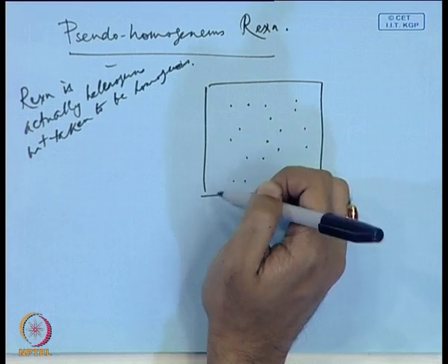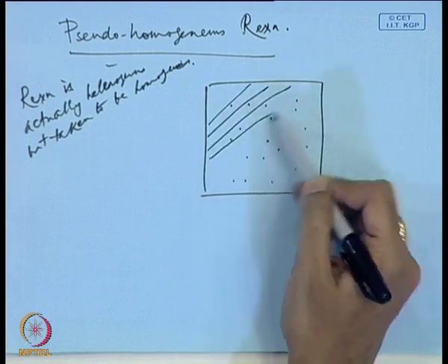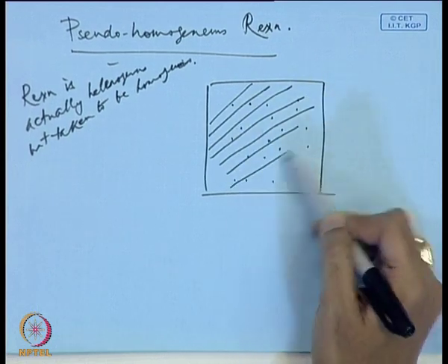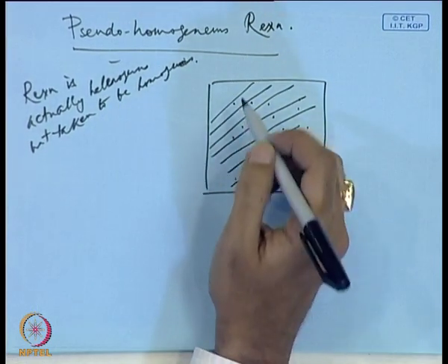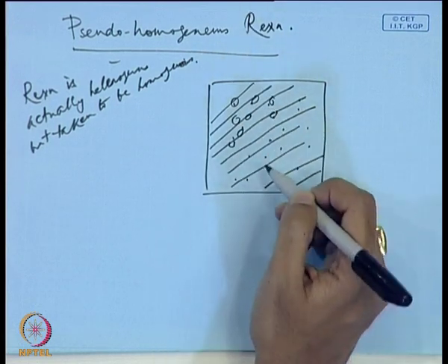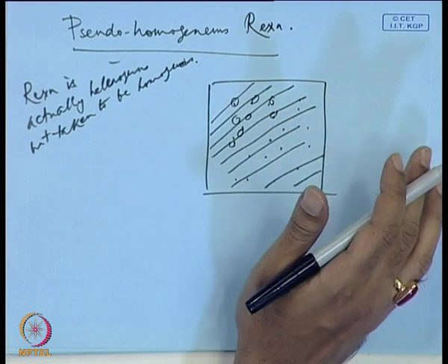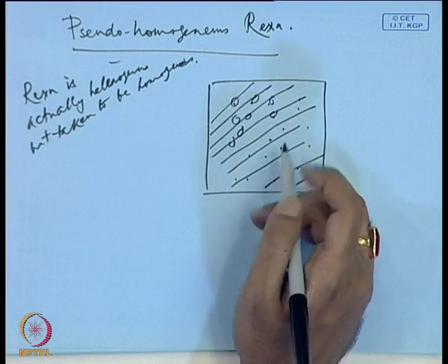So, what you do is you come up with a pseudo homogeneous model where you average out the reaction rate. At each point you have a certain reaction rate, but you figure out what is the total reaction rate in the system. What is the average number of pellets? So, you have say 1000 or 2000 pellets in there. What is the reaction rate for each pellet?